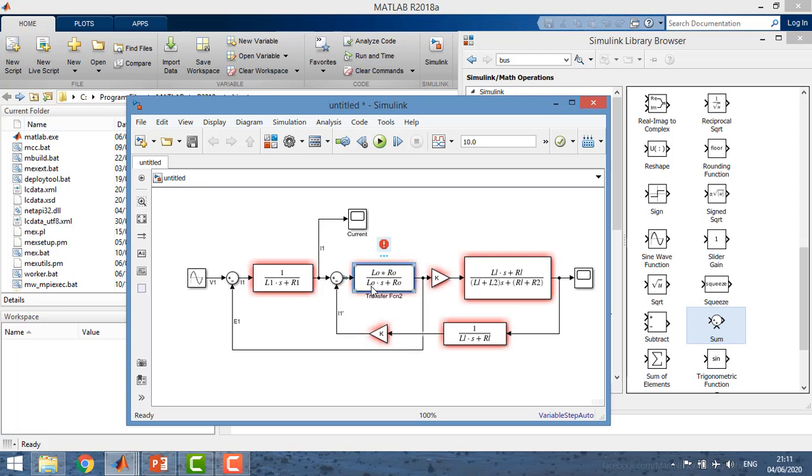We multiply the no load component by the shunt admittance to obtain the induced EMF in the primary winding E1, and when we multiply it by the turn ratio, the induced EMF in the secondary winding is presented.